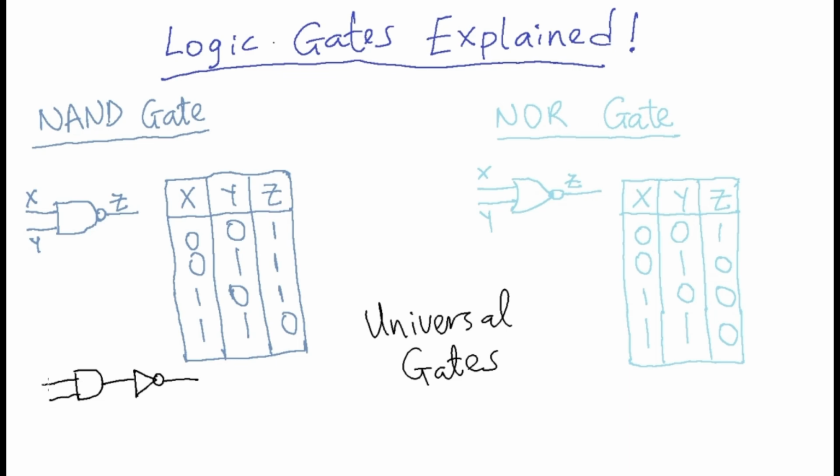So with our two inputs AND gate being fed into the input of a NOT gate, this is the same as the NAND gate, but for simplicity's sake, it is just represented as a D shape or an AND gate with a bubble in front of it, or a bubble at the output. So from this diagram here, you can just see that the output of the NAND gate is just the inverse of the output of an AND gate.